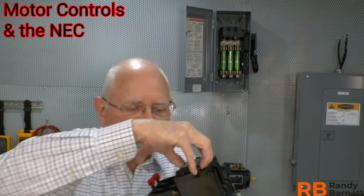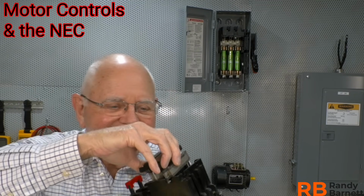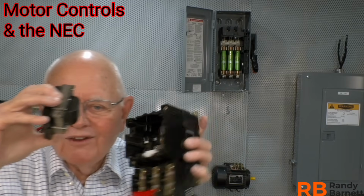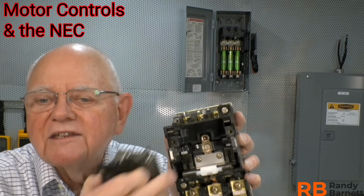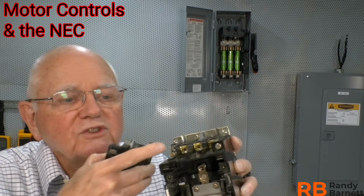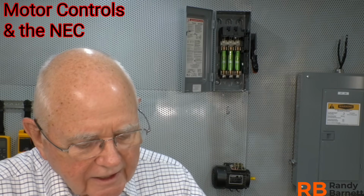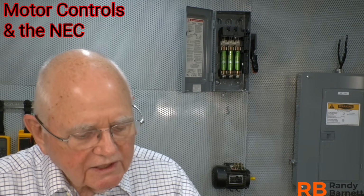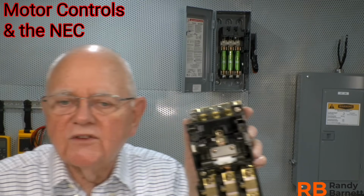I'll pull it out kind of carefully because it has some moving pieces associated with it. Alrighty. And so there we have the coil and we have the remaining part of the contactor. The contacts are back on the inside, and of course you can't see those right now. There are little screws on each corner up here, and there's a little note that tells me that I can loosen the screws in the corner in order to pull off the next section and actually access the contacts on the inside.